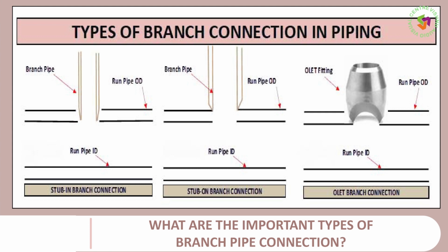After applying the correction for the discharge, again with this new discharge, we need to find the head loss, and again the net head loss in each loop. If the net head loss is equal to 0, then this discharge is correct.